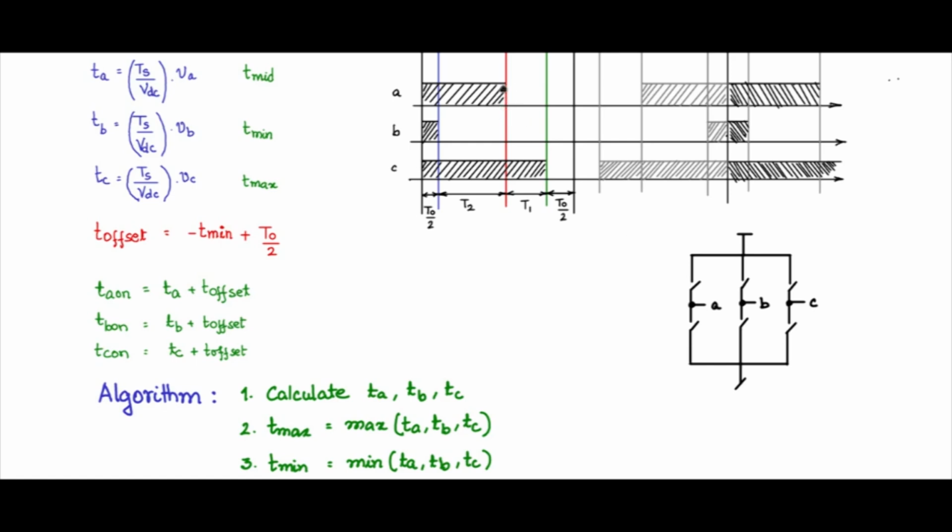At the transition, you will make a small time period called the blanking time period, where both will be off for some time, because this has to account for the rise time and fall time of these practical switches. That is called the blanking time or the dead time in the literature.